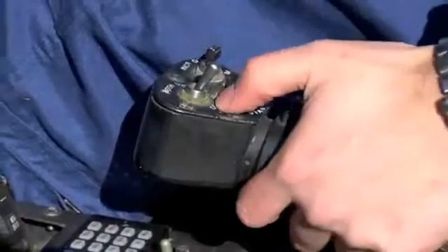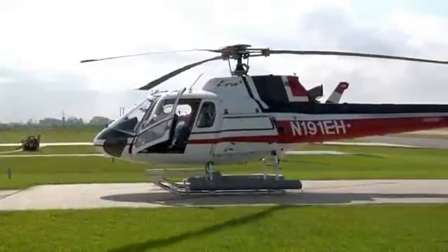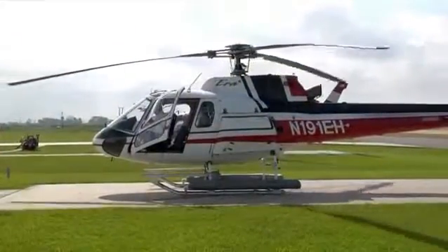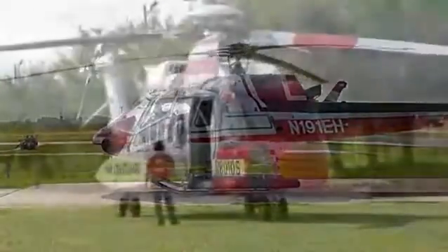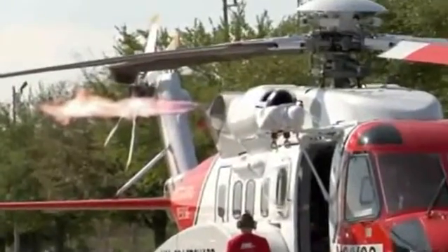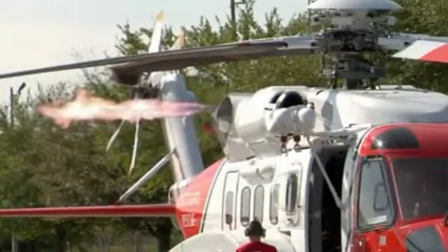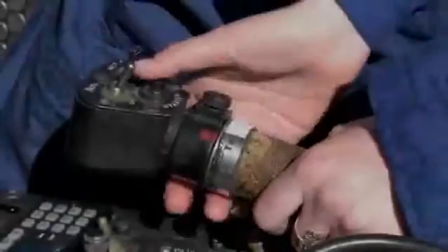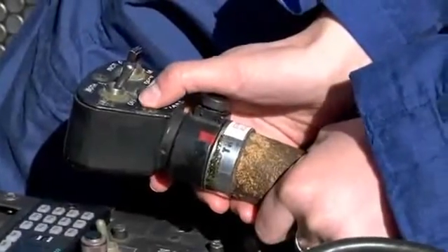An engine hot start can cost a company $100,000. But your pilots may have started the engine 1,000 times without ever having a hot start, and one day they go to start the engine, and it costs you $100,000. What if you had seen that your pilot had recorded 3 near misses with a hot start last month? It didn't hit 1,000 degrees, but it stayed over 800 degrees for a while.